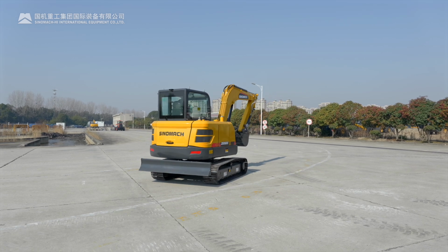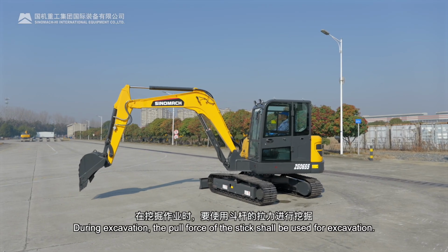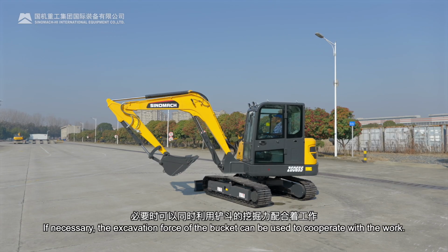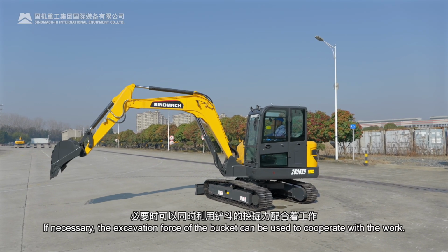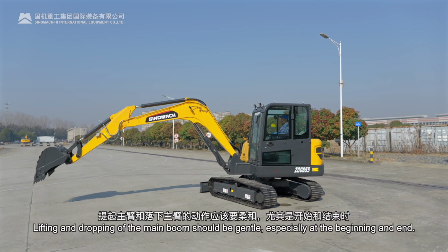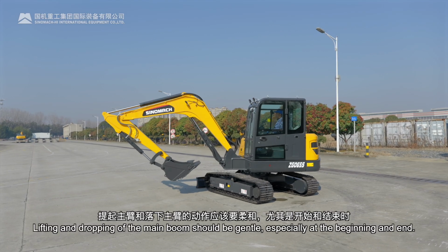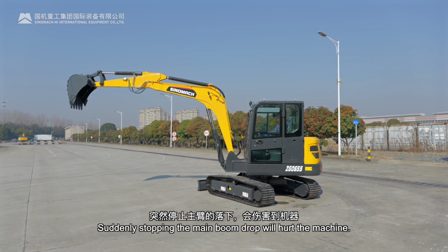in situ steering can be realized. Effective working methods. During excavation, the pull force of the stick shall be used for excavation. If necessary, the excavation force of the bucket can be used to cooperate with the work. Lifting and dropping of the main boom should be gentle, especially at the beginning and end. Suddenly stopping the main boom drop will hurt the machine.